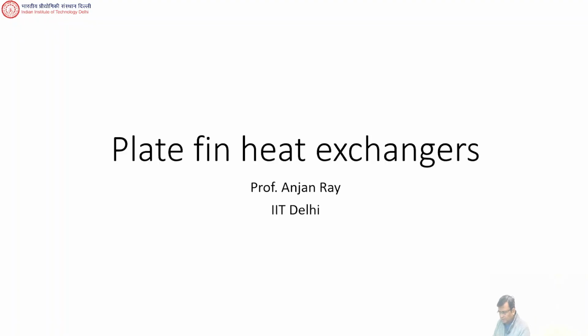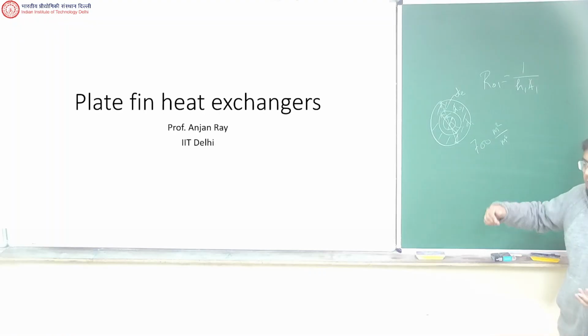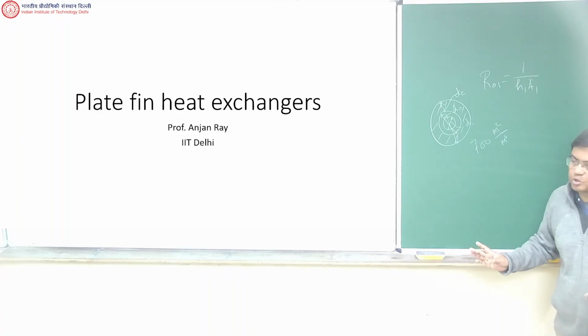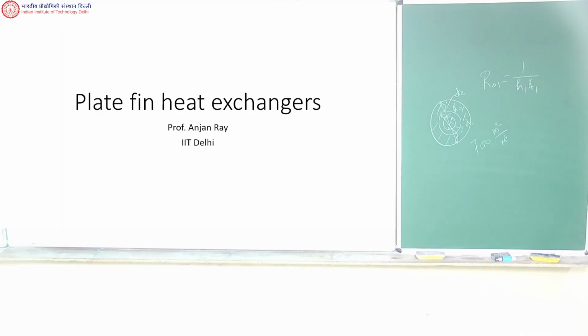So broadly, you see this, right? The geometry changes, isn't it? And if you can describe the geometry properly and do area calculations, then the rest of the process is similar, right? The shell and tube heat exchanger as well as the fin tube heat exchanger, it's basically the same sort of approach. Here also, the approach will be the same, but the geometry in this case turns out to be more difficult.